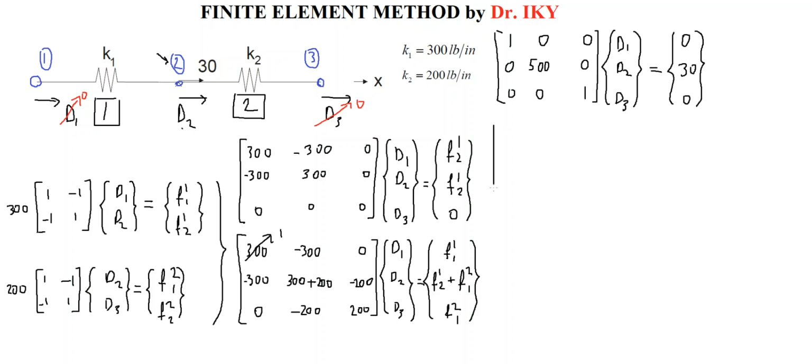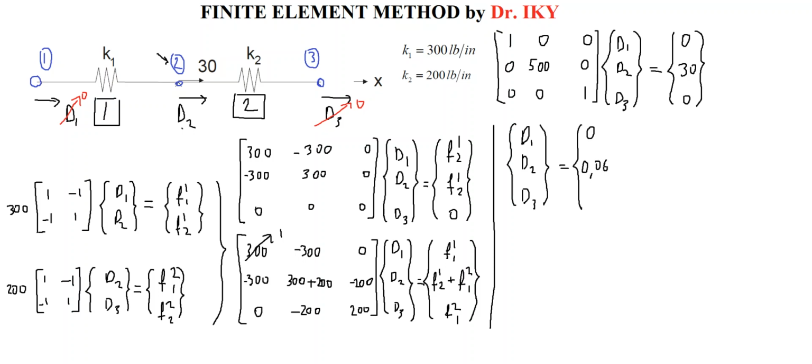So if I write the solution of the displacements, d1, d2, d3, it is equal to 0, 0.06 inches, and here again 0. So after finding these solutions for the displacements, I want to solve for forces,